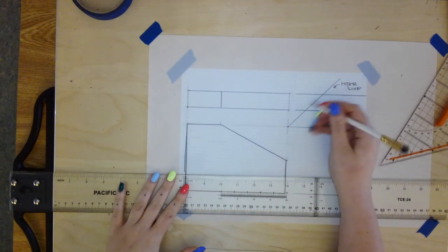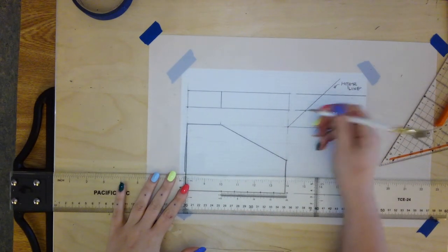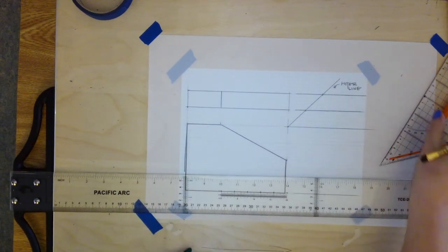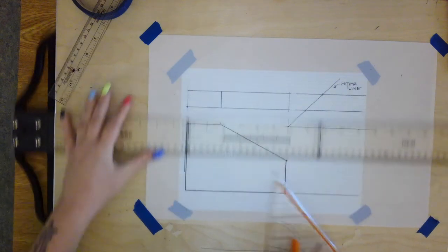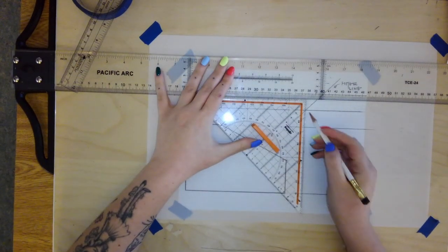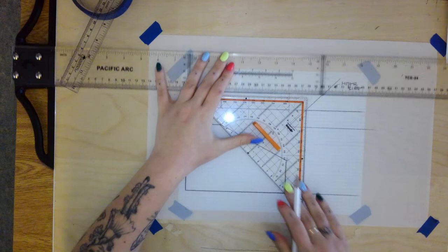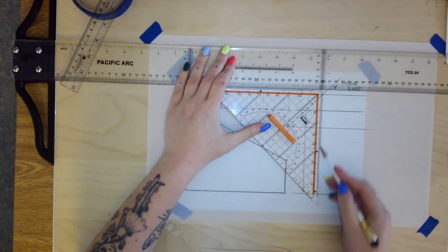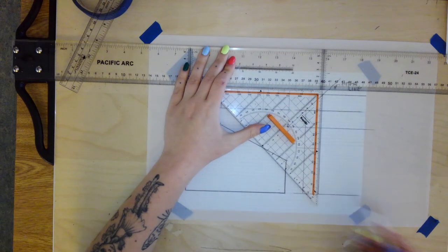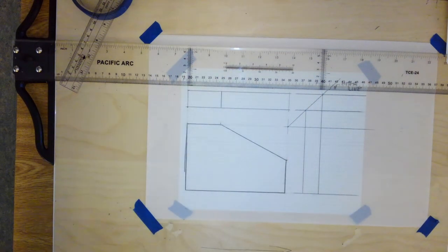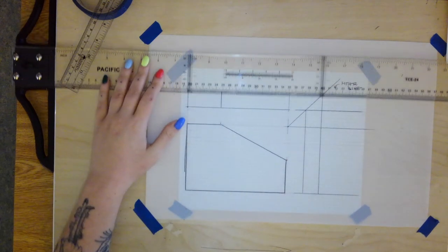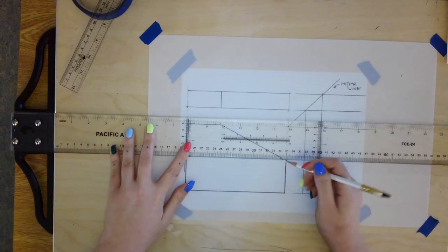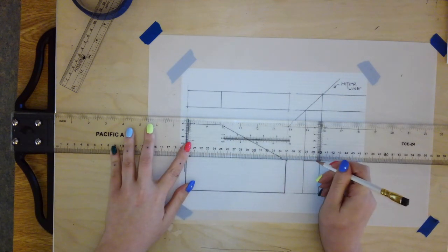So I project up at 45 degrees, and then where my projected guidelines come out from my top view, I'm going to project down. I'll make sure to send it out, and if I don't, please harass me about it, as I have lots of orthographic demo drawings of different objects, so I can send you different ones as well. And then I'll just need to make sure that I project this guideline over.